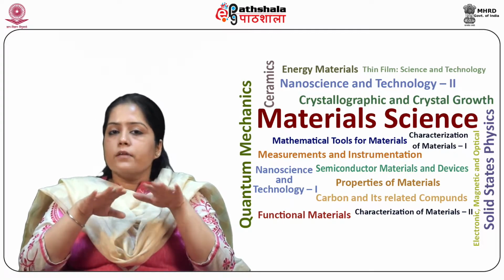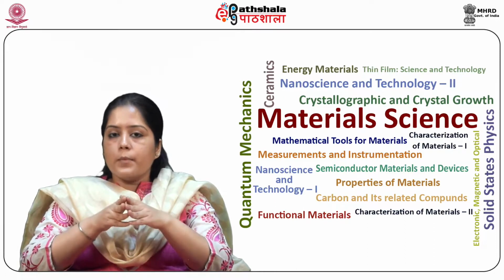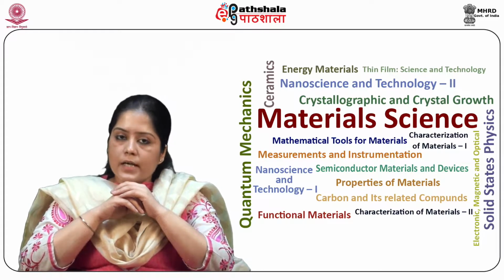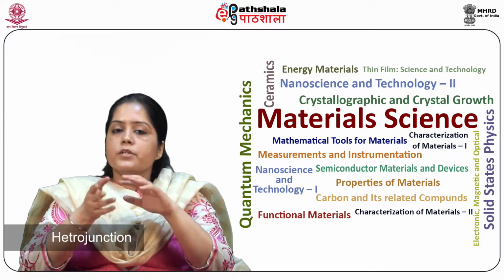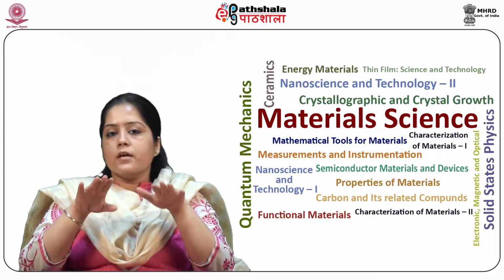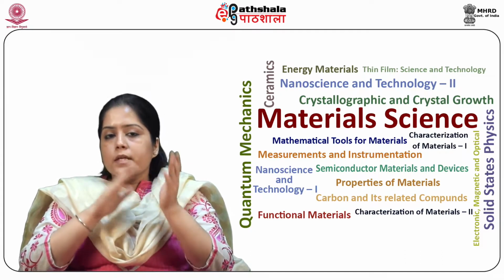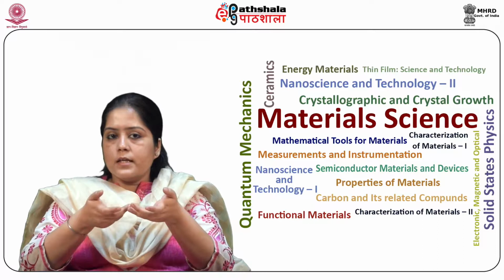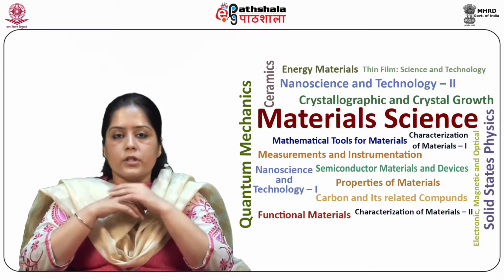There is a wide range of photovoltaic device structural possibilities apart from the shallow homojunction. Some alternative device structures have been described here. Heterojunction between two different bandgap semiconductors have no intrinsic efficiency advantage over the homojunction. The metal semiconductor heterojunction can be fabricated very easily. However, they are intrinsically less efficient than the homojunction.